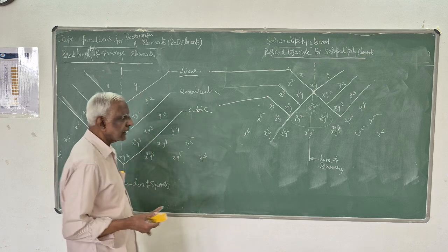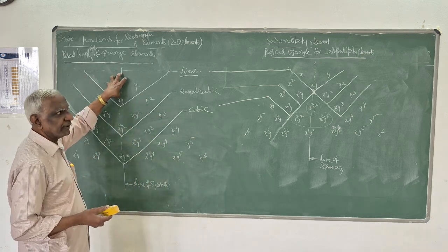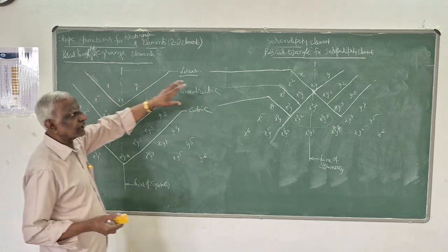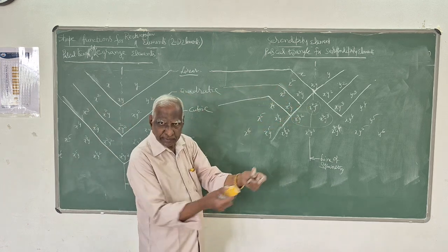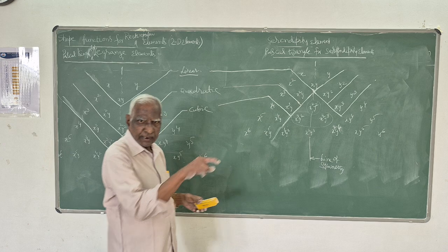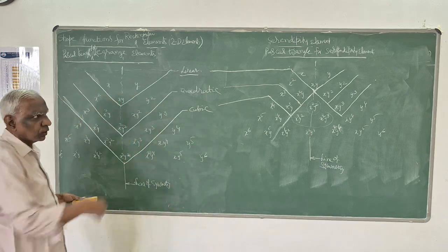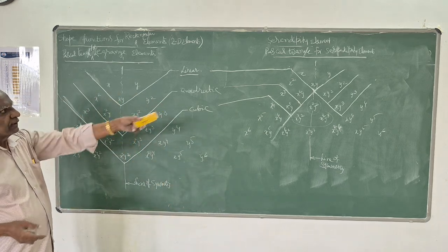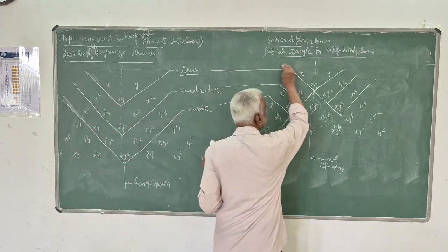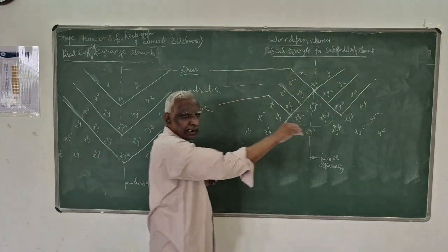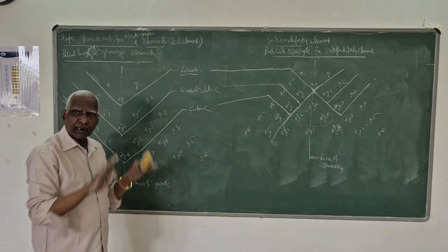From this we will clearly observe these elements are superior when compared to serendipity type of elements. Because if you write that polynomial equation for the degrees of freedom as well as nodes, you will find that only these terms are present and the functions will not be complete.